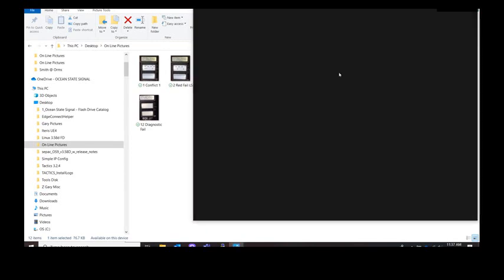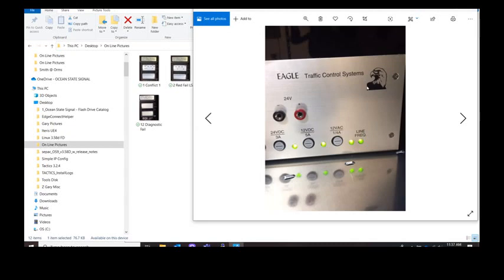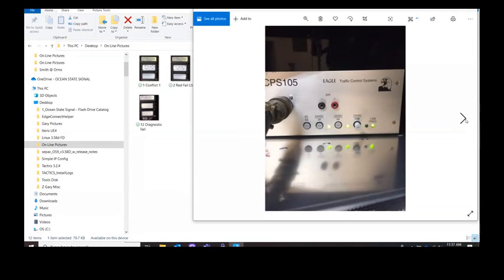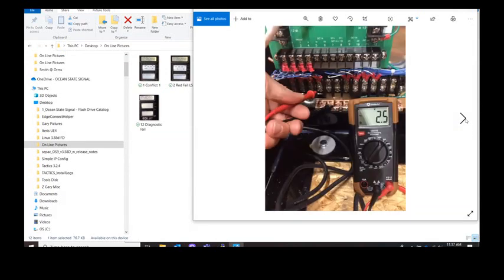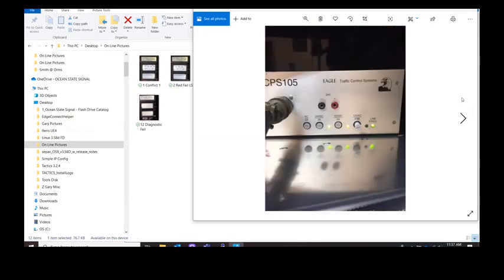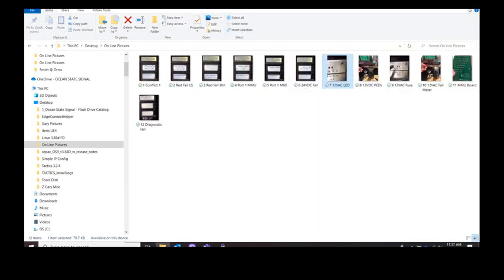Again, there's my 12 volts AC. I have my light on it. I measure it, it comes up 12.2 volts AC. I pull my fuse out to remove the circuit, and then I have 2.5 volts. Once I plug it back in, it goes back up to the 12 volts. So that's the 12 volt circuits. I know some people get a little confused on that, but that's how that goes. Okay, 12 volt circuits.